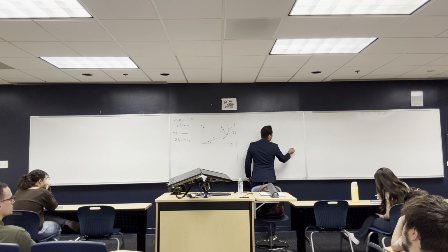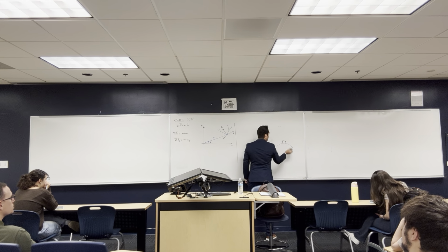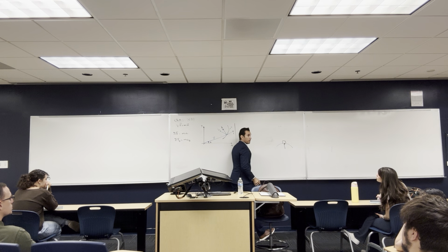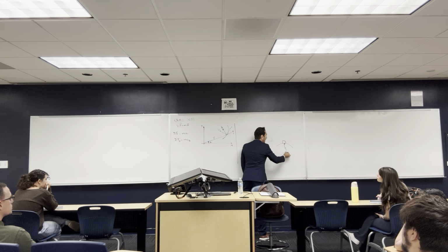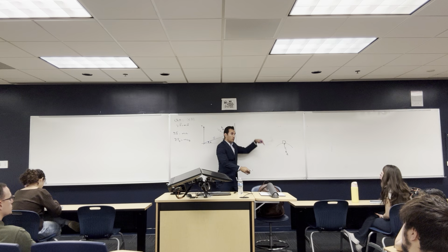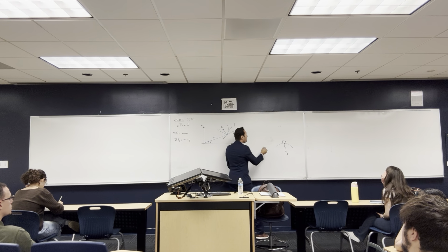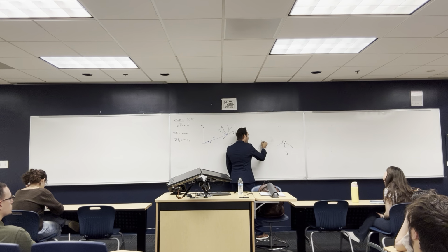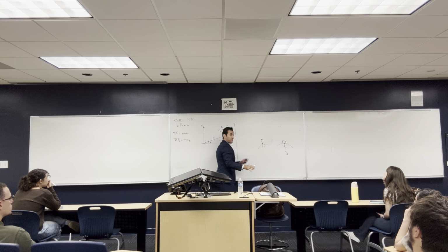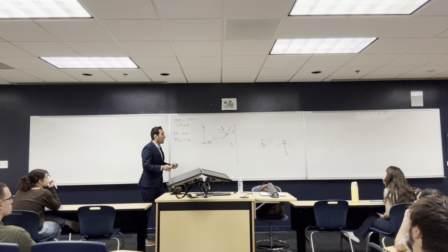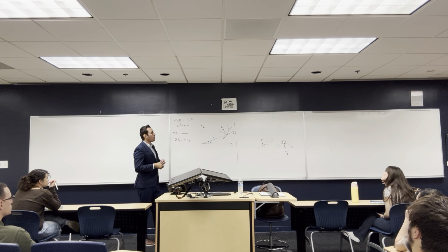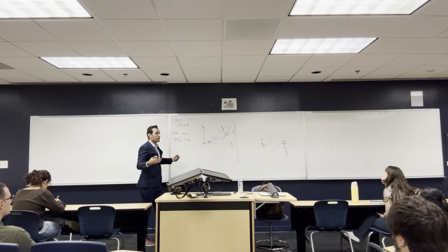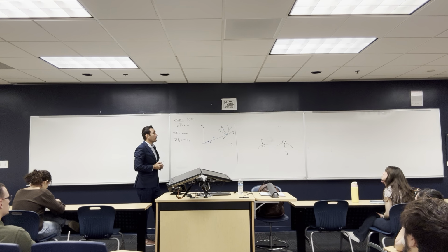Let's say my body is here, and that's my surface. It's a curve. The normal force is that way, right? The body weight is going down. The thing is, n hat is that way, always in the direction of the radius. But if my body is here, that is the normal force from the surface on the body. That's how you should do it. So sometimes it is the n hat direction or the negative n hat direction, but it's always positive or negative n hat. So that's the normal force.